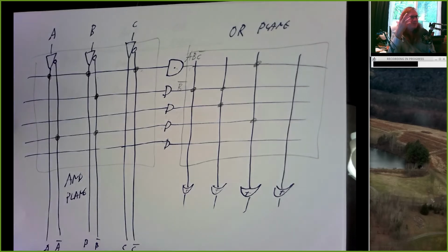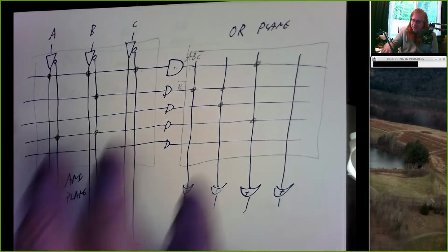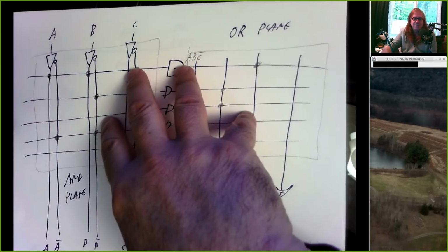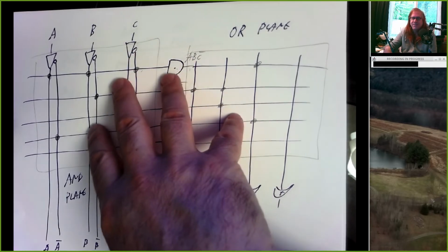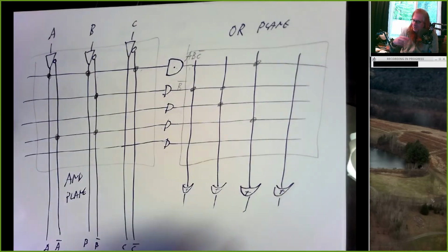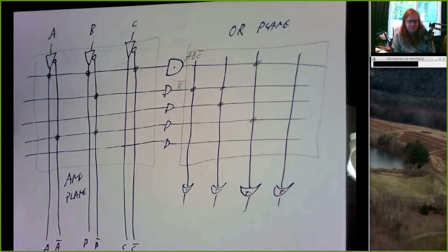So if you have some complex piece of circuitry like a traffic light controller with 6 outputs that are some logic combination of 3 inputs, you could get a programmable device, load those equations into it, and it would basically perform that function every time that you put power on it. It would take your inputs, generate those outputs. And this is one way that people can build circuits and systems without having to use protoboards or having to connect a lot of wires together to a lot of chips. You can take something that might take 15 chips and reduce it to a single chip.